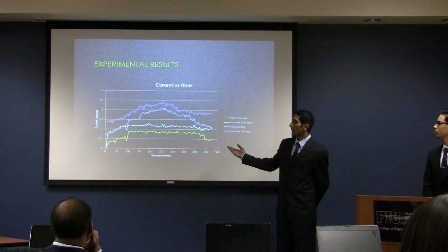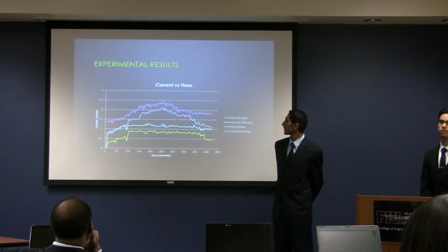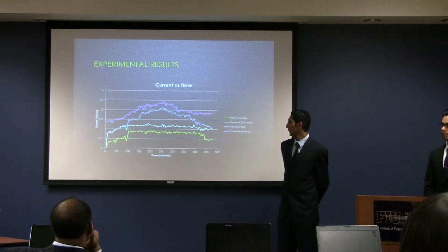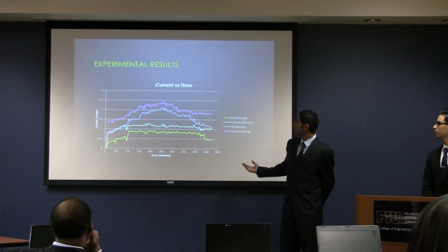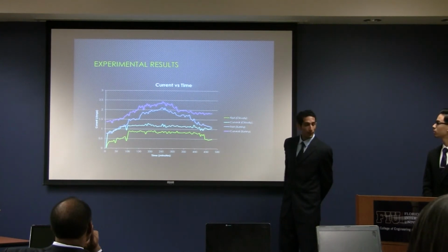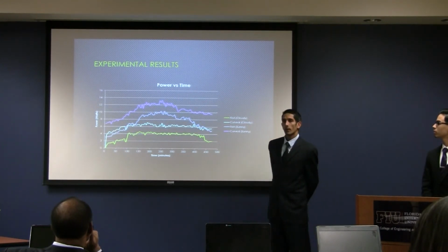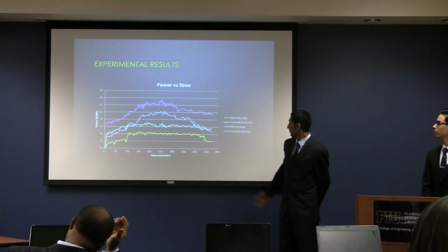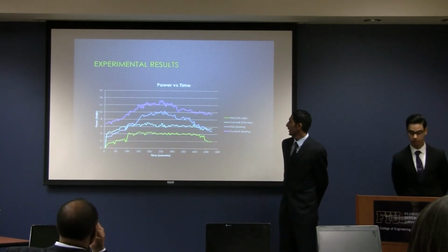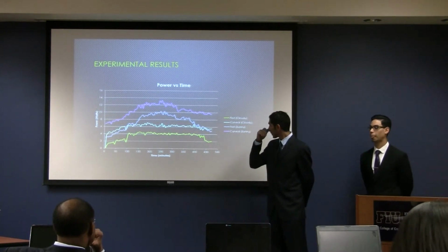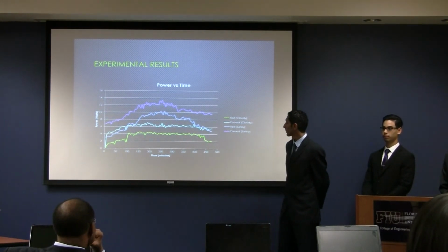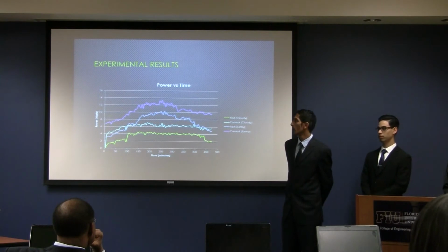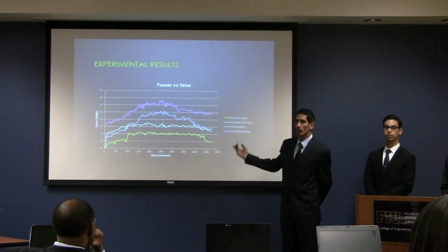as you can see, we did the testing again for two different panels for two different days, sunny day and the cloudy day. The current does change for the curved panel, but it doubled. And following up the power versus time graph, we calculated the power by the product of current and voltage for two different panels as well for two different days. And then, after doing the power versus time graph, we calculate the energy generation by integrating under the power curve.